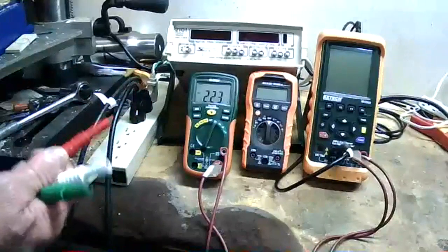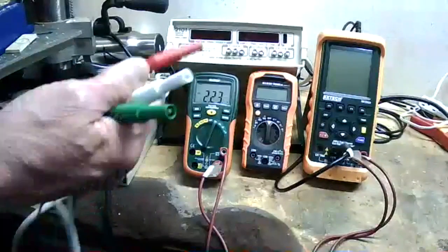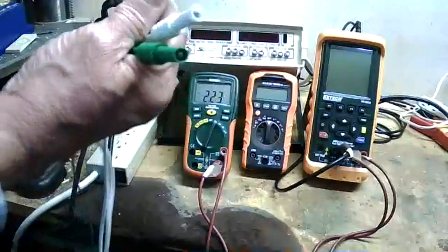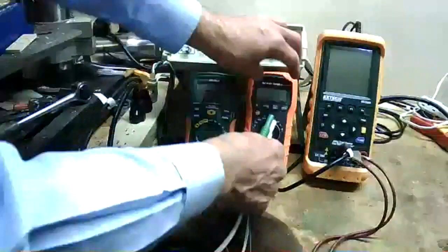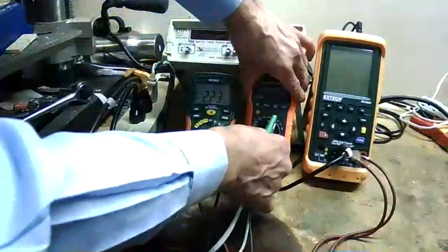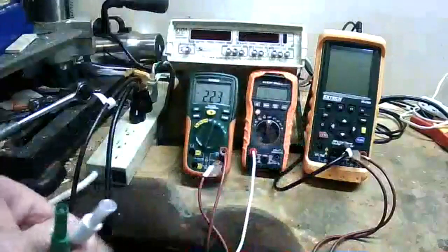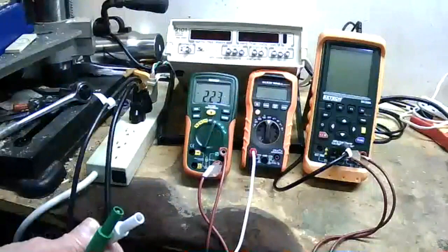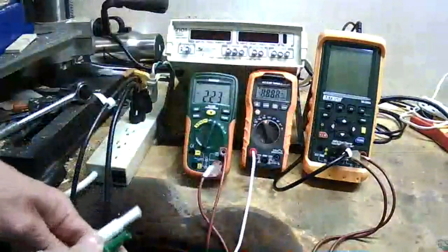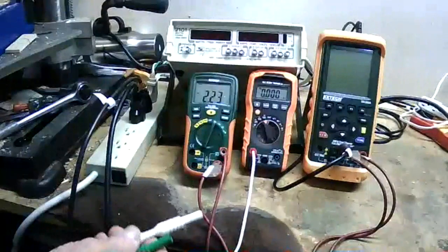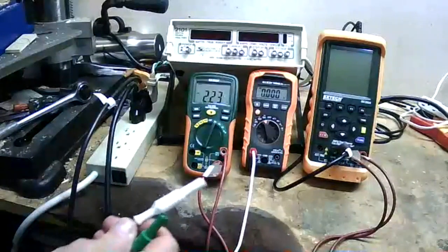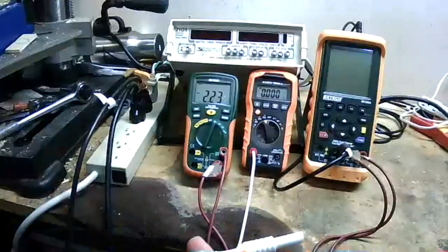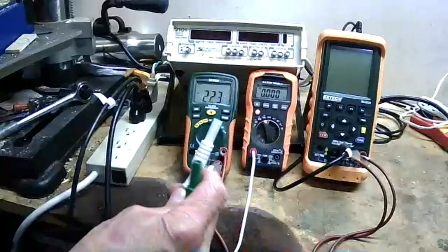So to get the power to the drill press, I'm going to plug the energized conductor into the amp connection, the 10 amp connection on the other multimeter. I will set that to AC and DC amps. It's an auto-ranging multimeter. It detects whether it's AC or DC. I don't have to tell it.